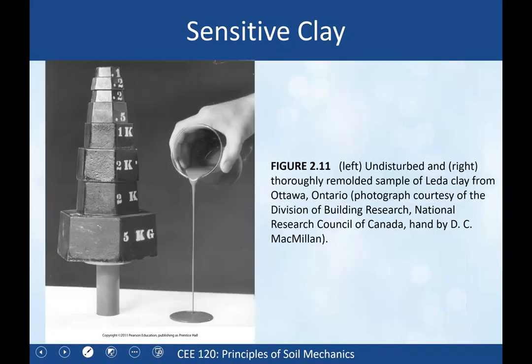All right, the last slide that I'll show for Atterberg limits is an aspect of clay behavior that's related to the flat, plate-like nature of clay minerals, and it's sensitive clay. There was recently a landslide in Norway that you may have seen in the news that happened in sensitive clay. What this slide is showing is a little cylinder of soil, looks like a triaxial test specimen or something, and it has a certain water content, and it's supporting all of these masses, right? 5 kilos, 2 kilos. This is a lot of weight. So this little soil cylinder is pretty strong.